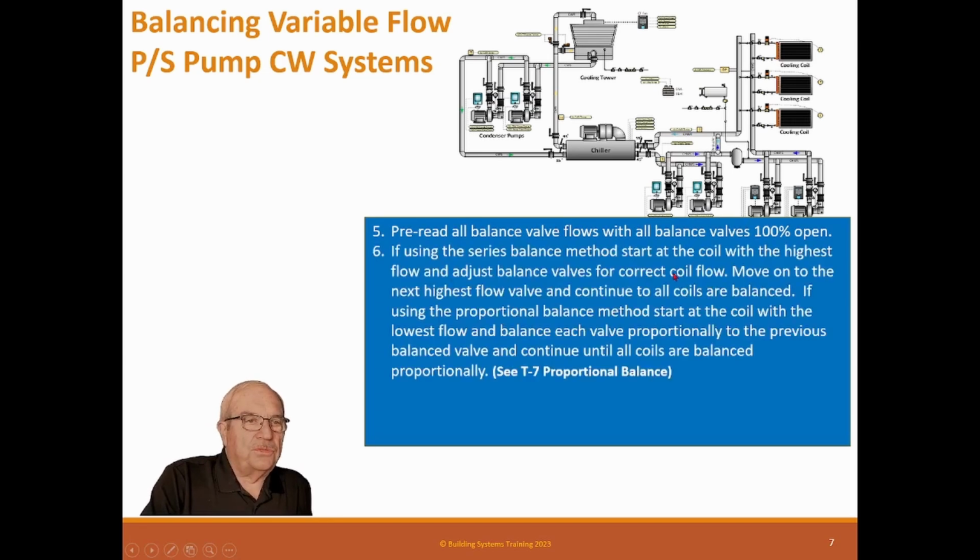When you're starting out, if you're using a series balance method and you're starting at the highest valve, you have to look at the valves. If that's a very big valve, then you can balance it down and watch what happens. Now, in both situations, series and proportional, you will have a target valve, and it will always be the valve with the lowest percentage flow. You don't touch that valve at all, because as you balance you're going to push water to it. The series method is kind of a hunt and peck method. It doesn't actually proportional balance, but it does balance, and both of these work.